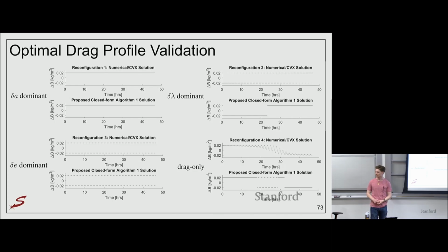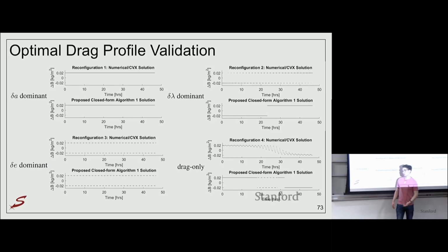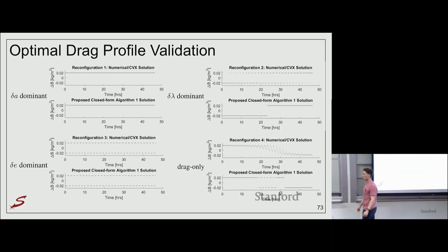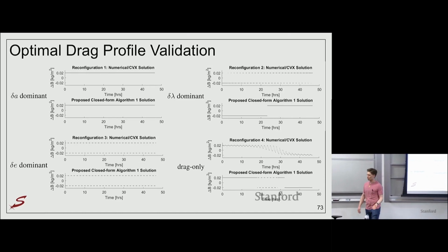This almost reminds me of atmospheric entry. Mm-hmm. You'll see similar very strange profiles on atmospheric entry trajectory optimization. Yeah. And that's another benefit of doing this in a closed form way, is that we don't have these kind of very numerical profiles happening. Like to your point about the changing of the attitude, yeah, it's fairly instantaneous, but we don't want to be doing it that often. So this is not really realizable in an effective sense for a fairly cheap CubeSat like we're going to be using for SwarmX.